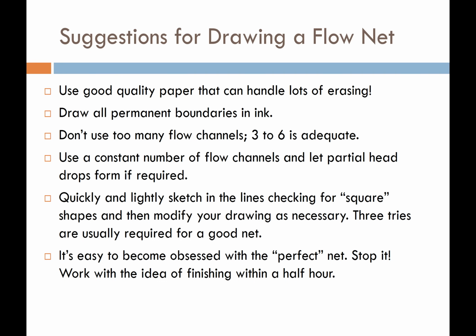Okay, so here's some very practical suggestions that I want to give you for drawing flow nets by hand. We discussed the rules, and now these aren't rules, these are just tips that are going to help you hopefully. The first tip is I recommend that you use some good quality thick paper that can handle a lot of erasing. Don't use flimsy engineering paper or recycled paper. Running your eraser over that a few times and you're going to rip a hole right through it.